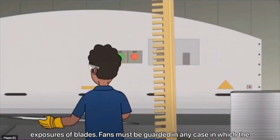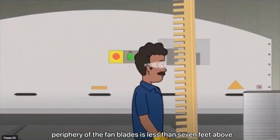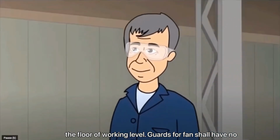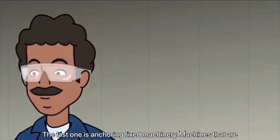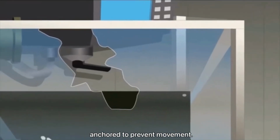Exposure of blades. Fans must be guarded in any case in which the periphery of the fan blades is less than 7 feet above the floor or working level. Guards for fans shall have no openings that exceed 1/2 inch. The last one is anchoring fixed machinery. Machines that are designed to be fixed in one location must be securely anchored to prevent movement.